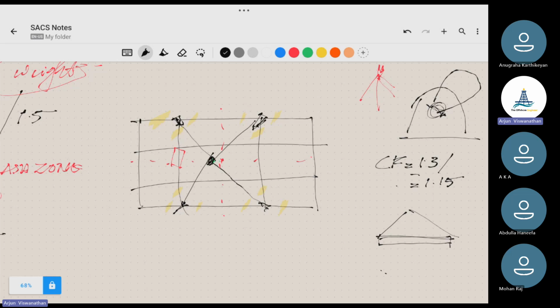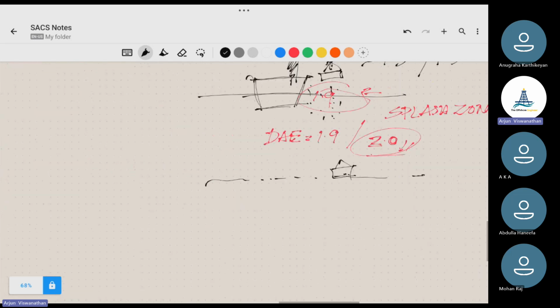But in some cases they will intentionally tell us they want to lift the structure in an inclined position. In that case, we can go for inclined. Now, when we select the rigging, we are taking it from the COG location and hook height. If my COG shifts, there will be some imbalance from what I estimated. So if my COG shifts over here, there will be imbalance on these slings and some failure can occur. To avoid that, we consider a COG shift factor.